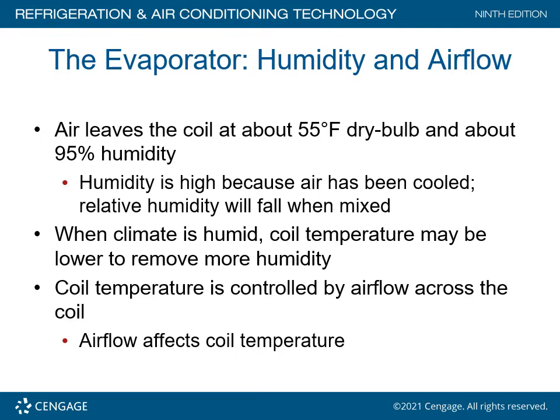Okay? When the climate is humid, such as Augusta, Georgia, the coil temperature may lower to remove more humidity. Coil temperature is controlled by airflow across the coil. Airflow affects the coil temperature. Well, how about the more air, the better?